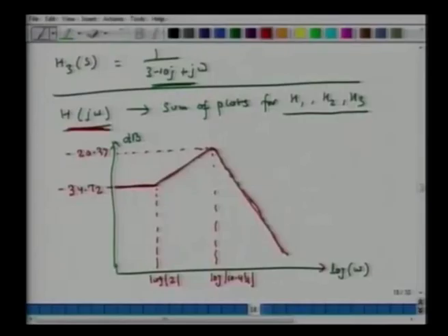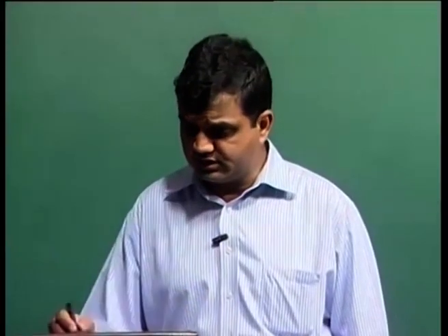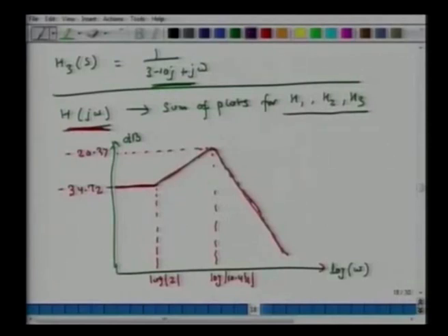Now again, this is an asymptotic response for the magnitude. The actual response is not the same as this dark red line. If we actually plot the actual magnitude response, that is shown here in the purple line. So asymptotically on this side, the line converges to the red line. So this is the asymptotic response. The actual response is something like this. And at infinity, the red line and the purple line converge and meet.